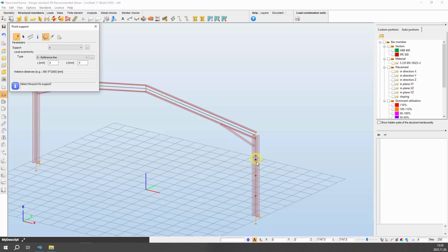Placing supports into specific points of the structure can be hard sometimes, but adjusted snapping point distribution can help in accurate object placement. Snapping points are represented with red dots on a structural object. You can adjust snapping point distribution settings at the bottom left according to your preferences. Options include setting the n value to divide a structural element into equal length sections and the d value to divide a structural element into sections of exact length.